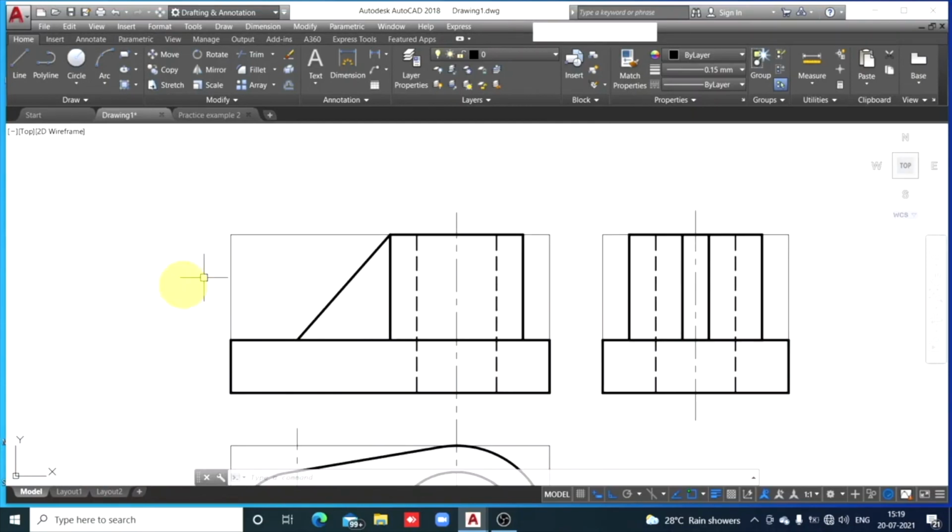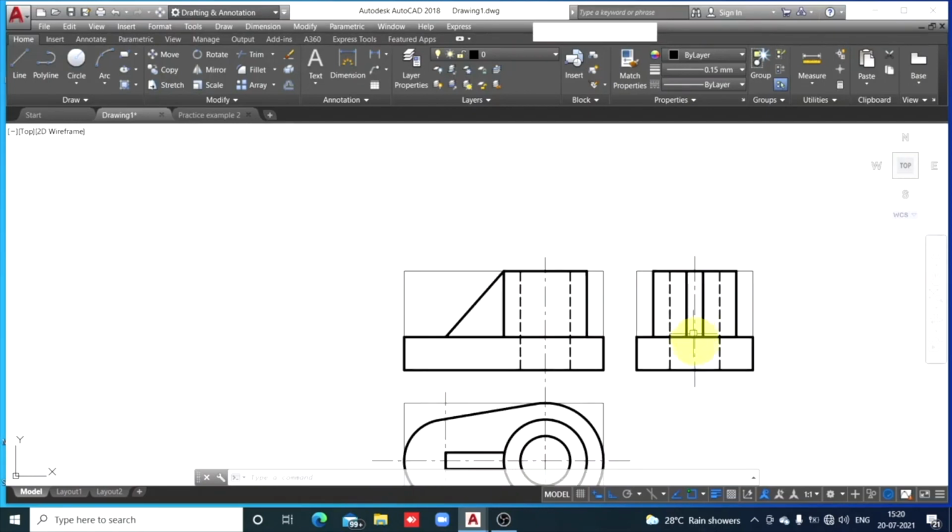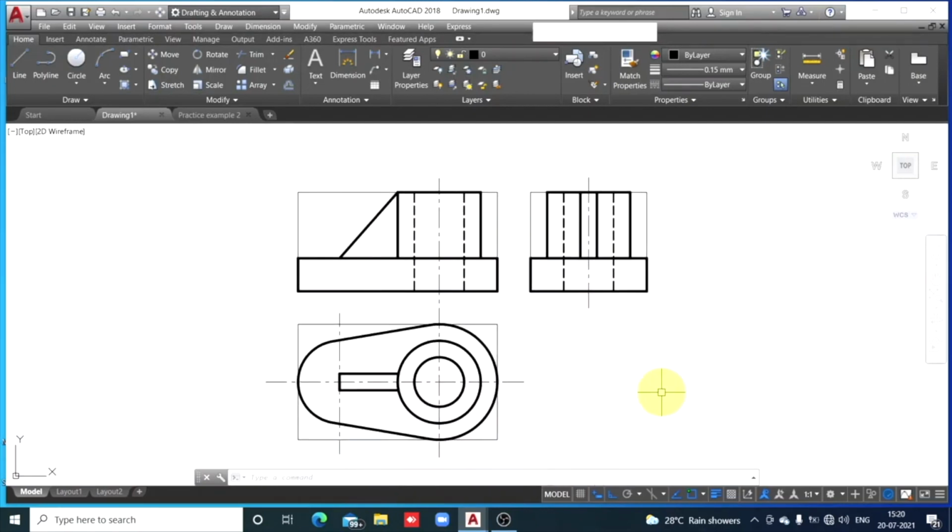Now from the left side, this is the left side view, the observer is watching from the left. So this triangular plate is visible, so don't draw this triangular plate hidden, it's visible. So dark continuous lines are correct. Had this triangular plate been on the right side, then we would have concluded that it is a hidden plate and we would have drawn these two lines dotted. Okay, so this is how we have completed the drawing.